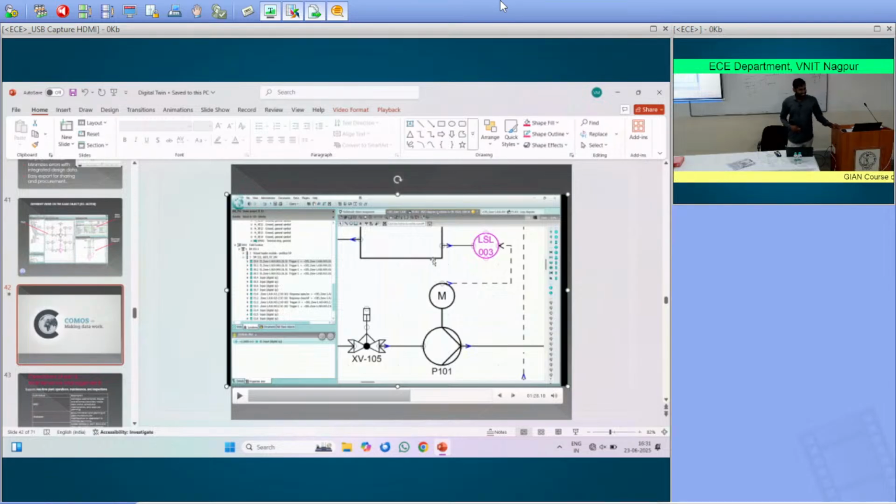I think Proteus is a software where all the microcontrollers are available. You just take the microcontroller, and the way you program it is the way it will be programmed in the real world. You can simulate a similar environment there and see whether the outputs are right. It is only software. Let's suppose you want to work on a microcontroller: you drag and drop it there, write a program accordingly, and it will show you the output. Let's suppose you want to blink an LED. The LED also has to be dragged there, and it will show you the same output. Later, when you try it on your real product, it will work fine. So it is to test the program.